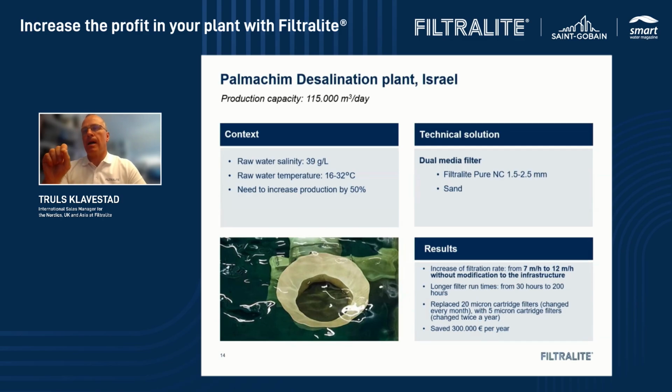At the same time, they also increased the time between the backwash from 30 hours to 200 hours. So you have much more suspended solids coming in because you increase the filtration rate, but still you also increase the runtime between the backwashes. On top of that, they also saw some benefit further up in the process.